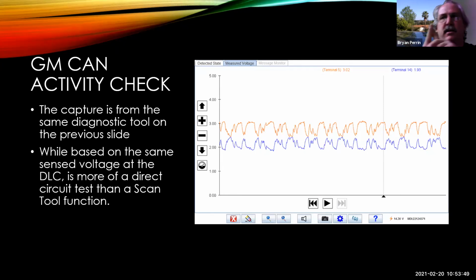The other thing it does is allow the computer, when it gets both of these signals, to see if there's a problem on one of the lines, because this is redundant information. We're sending the same information on CAN high as we are on CAN low. When it gets to the receiving module, it looks at both and asks, do both the reports match?